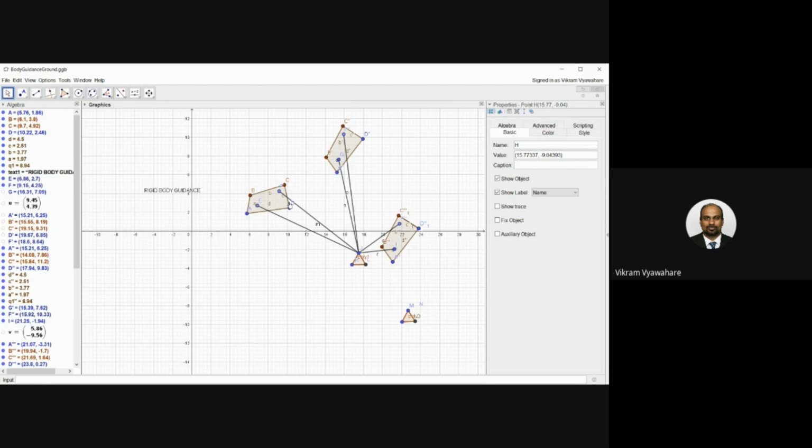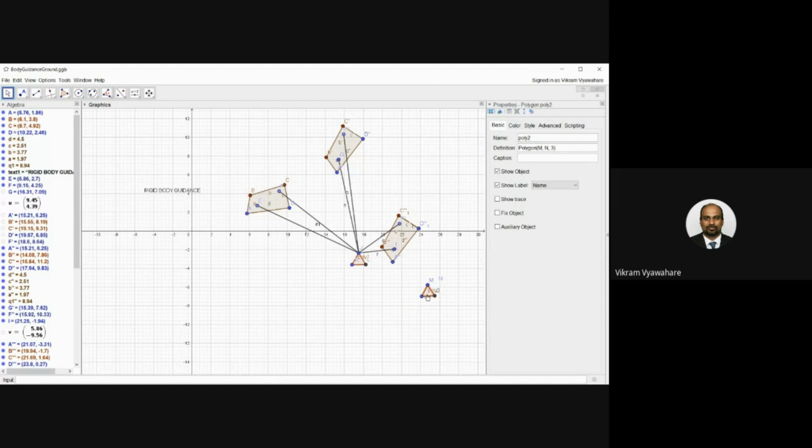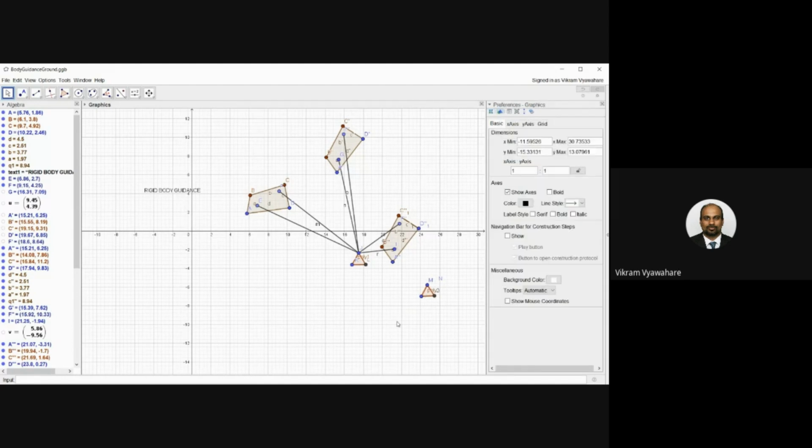So there is a 4-bar mechanism, right? You have to visualize that there is a 4-bar mechanism right now, and there is a coupler which is having these points. So what we are going to do is we are going to fix this link, which means other links will move. So other links will move means I can use this triangle. This is the triangle which is formed in this location. So I can draw a similar triangle and actually move the pivot point. Now the pivot point is not stationary for the inversion, and we are going to fix this link. Okay, the first link we have fixed.